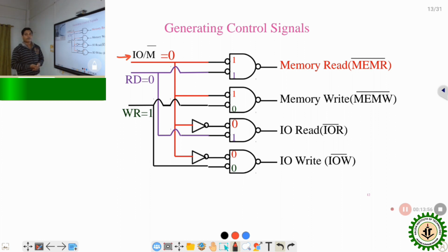That is, when the microprocessor wants to access the input output device, this signal will be high, or logic level 1, whereas during access of a memory device, the control signal will remain low. That's how the processor separates input output devices and memory devices.